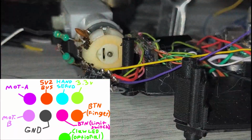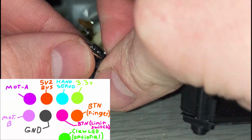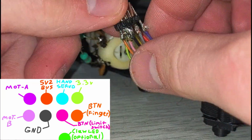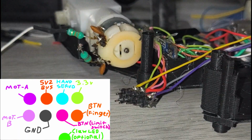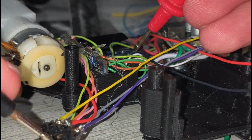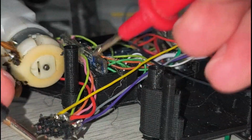But other than that, you just hook up the limit switch to button 2, and you connect the fingertip button to button 1, and then you connect the 3.3 volts to where it goes and the 5 volts and grounds where they go. And then you have motor A and motor B. We'll worry about PWM, motor A, and motor B later.